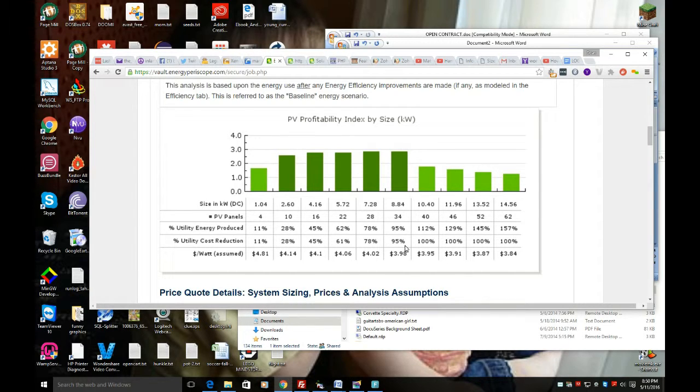I do not know how things are in Colorado, but in California, you do not want to go over 110%. It creates a huge snafu. Normally, the systems we install are slightly hotter than what's on the proposal. So if you rate a proposal at 105% and we push over that 5% amount when we're designing the system to be permitted, and it goes over the 110, the power company has the right to deny us.